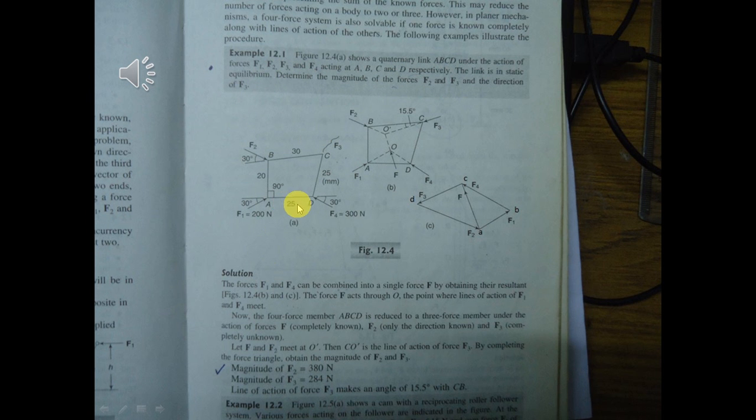Okay. Now we will proceed by drawing a diagram, that is AB, based on the given data. First you draw AB and AD, and using a compass you have to mark C, that is 25 mm and 30 mm, so we make an arc from here, and also from here, until there is the meeting point of the arcs. You have to extend DC and BC. Thus you will be able to draw the link 25 mm as well as 30 mm.